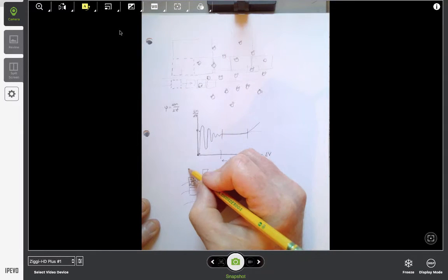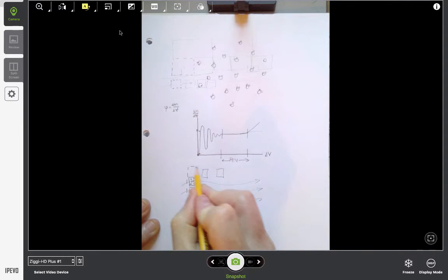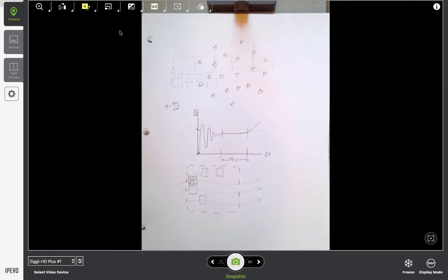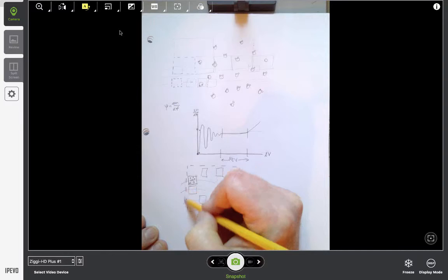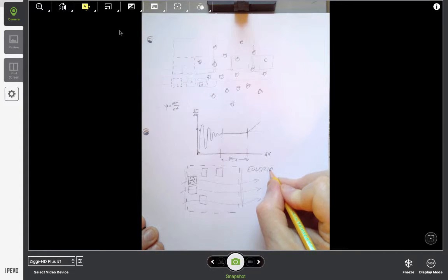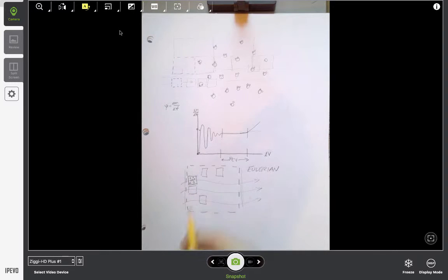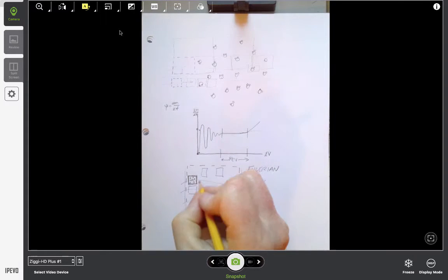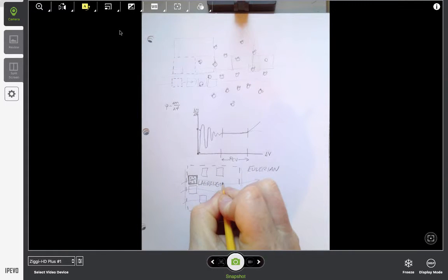And we might also have an area in space represented by this dashed line where we're interested in the behavior of the parcels going through that. If we're interested in this dashed line and we're counting parcels coming and going, and we don't really care about the identity of a particular parcel, we just want to know how many enter on this face and how many leave on this face. That's called a Eulerian reference system, for lack of better words. If, on the other hand, we're studying the behavior of individual parcels and the path they take, that's called a Lagrangian coordinate system or reference system.